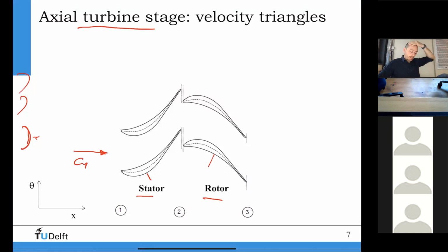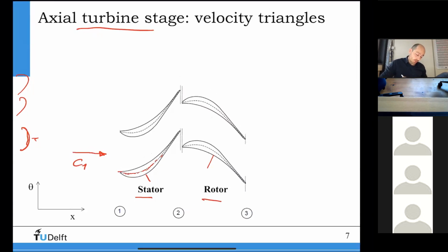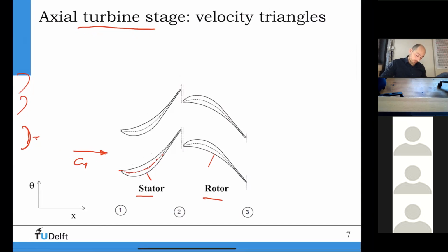Okay, it's not a blade. Blade usually is for the rotor, which moves. For the stator, it's a vane. And the camber line is this middle line here. And so if you assume that we have no losses, no flow separation, no boundary layers that build up along the stator blade, then we can say that the flow is simply going to behave like an Euler fluid, right? And it will just follow the blade angles. The flow goes in here, and it will just follow the blade angles.